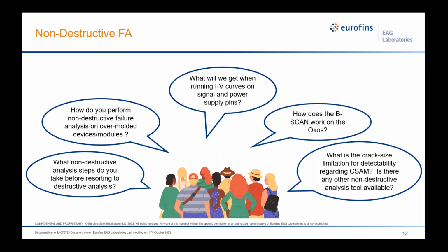Yes, sure. Yeah, we do IV curves to see what the shape of the curves is, and it's very useful for failures like continuity failures or power shorts or pin leakage. So by looking at the IV curve shapes, we can get a good idea what we're looking at. A lot of times we compare with a good unit, and other times we receive defects or rejects, not directly from ATE tested parts. So the parts are pulled off from a board and they just say, oh, this part failed on the board.